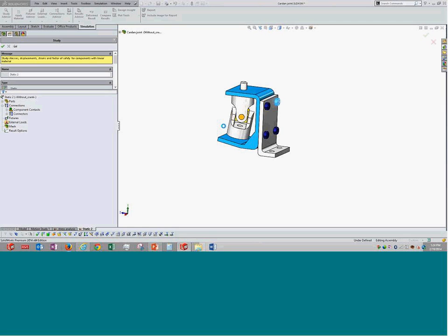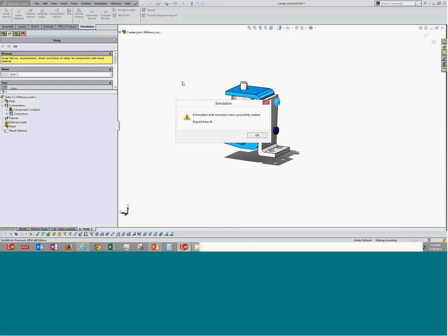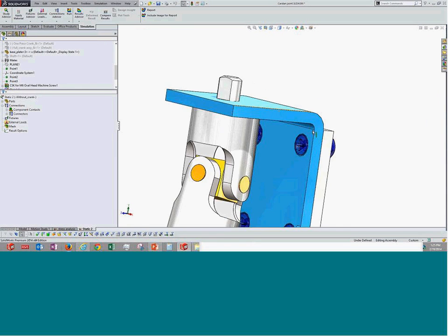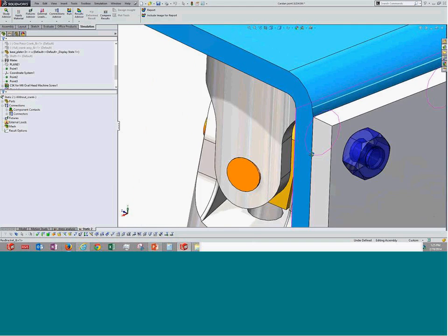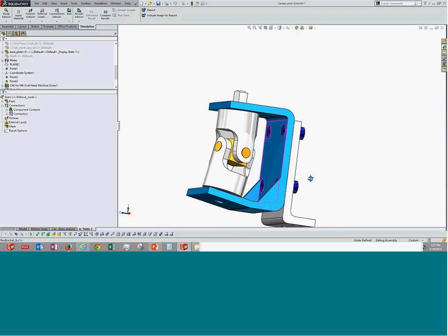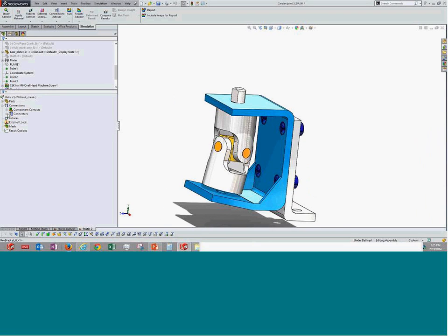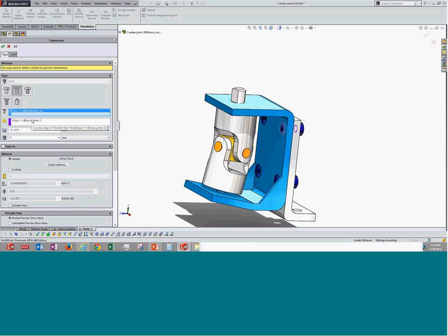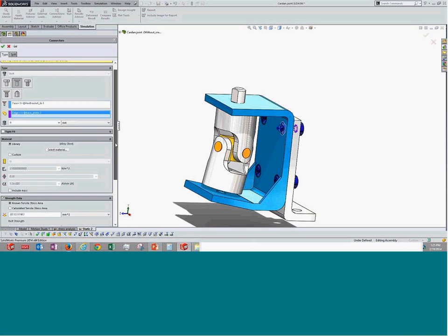Now, the blue color bolt that you are seeing is more for visualization. There is no such bolt present there. It is just a connector, for giving connections. Now go to the settings of those things. This all happened automatically. Be aware that when this training manual was written, or before that, this option was not present and we used to do it manually. So all dimensions have been taken, the appropriate bolt connector is selected, and all the details come into the picture here.